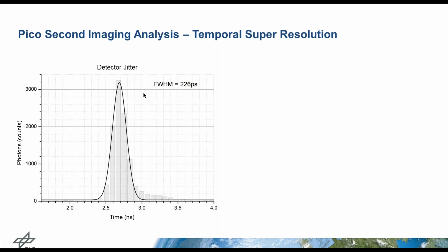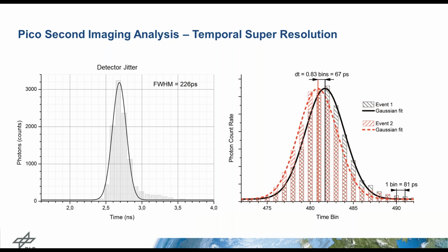We repeat it quite often. And then let's say we change something. We make sure that maybe another transistor is involved in the propagation chain of the signal. And so we expect, if we do the measurement again in the second configuration, that there is a slight change in time. And we repeat the measurement again 1 billion times. And what you get then is something like you can see here.